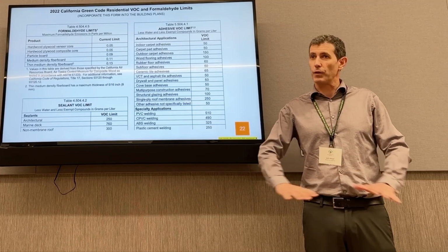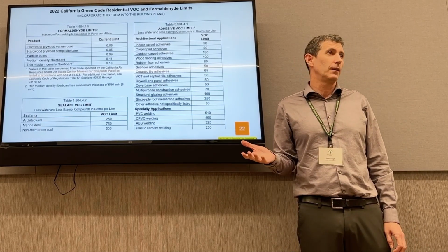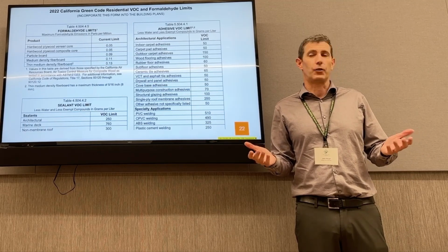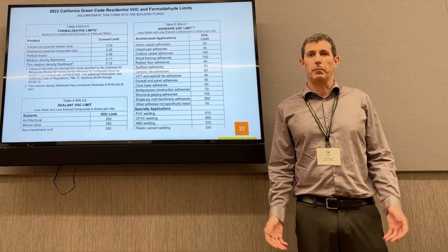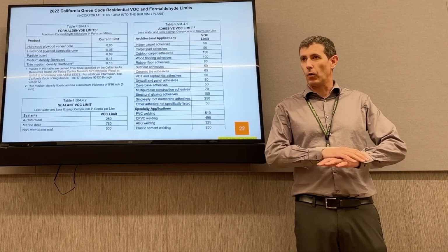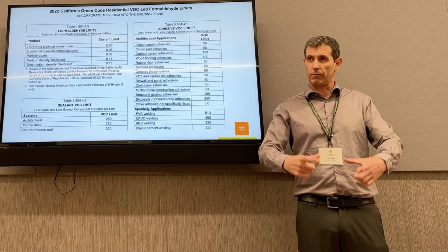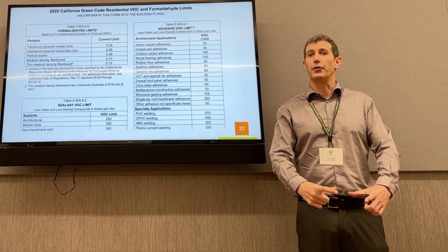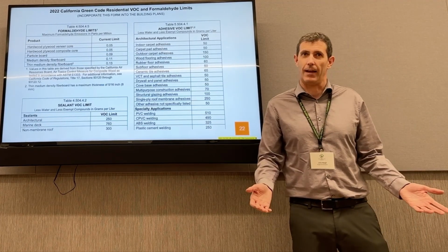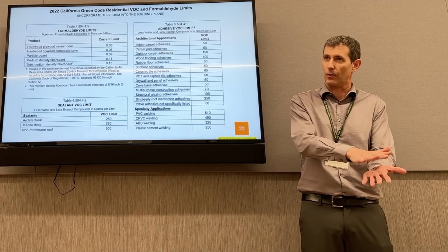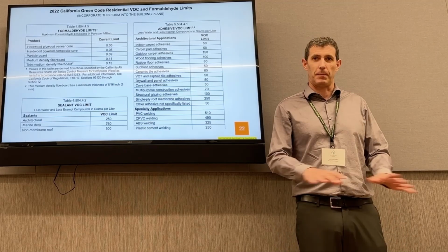You may be going over some of those things, encapsulating some of those things. But like the house I was at this morning, the contractor went through and stripped off all the tile off the floor, and lo and behold, almost the whole bedroom wing of the house had 9-inch linoleum tiles underneath that he chipped and cracked and broke, and you can see the black mastic used to hold those tiles down. It's all scraped from the demo work, right? That's all asbestos-containing material.